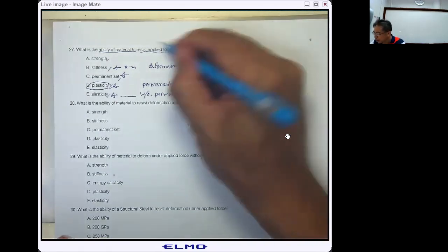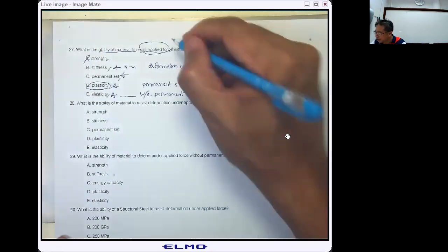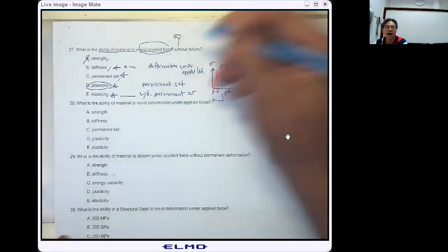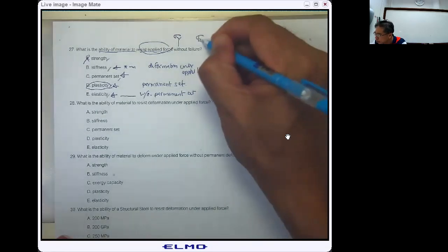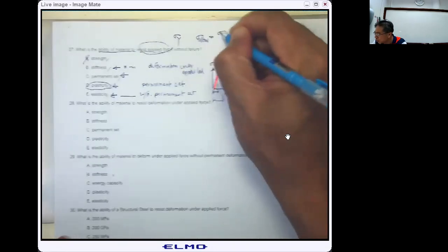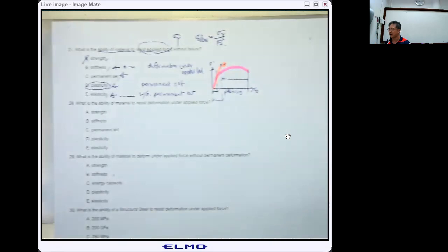So when we're talking about this one, we're talking about the strength, and usually we use the sigma sub y as the strength of material, and by doing that we use sigma equal to the yielding divided by factor of safety that represents the strength of the material.